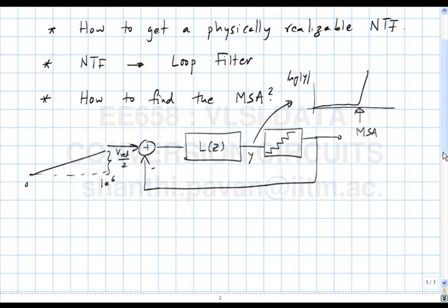One thing, of course, which we can understand still at this level is the fact that as the number of levels becomes larger and larger, the approximation of the quantizer being a linear system with this additive noise, that model becomes better and better. And you've seen this from your simulations on quantizers and so on. You've seen that that's the trend. And fundamentally it also makes sense, because if you had only a 1-bit quantizer, your basic quantizer is doing such a sloppy job, and you have to clean up after the quantizer by doing a lot of noise shaping, right? So presumably if your basic quantizer is doing a reasonable job, you'll be doing much better. That's all that there is to it. So we figured that out.